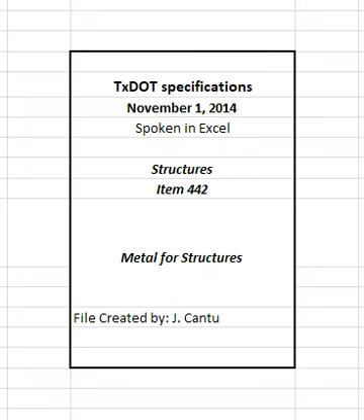Over 2 inches to 4 inches, mechanically fastened: 15 feet-pounds at 70 degrees Fahrenheit. Over 2 inches to 4 inches, welded: 20 feet-pounds at 70 degrees Fahrenheit. Any steel with minimum specified yield point over 65 ksi and under 90 ksi,2 up to 2.5 inches: 20 feet-pounds at 50 degrees Fahrenheit. Over 2.5 inches to 4 inches, mechanically fastened: 20 feet-pounds at 50 degrees Fahrenheit. Over 2.5 inches to 4 inches, welded: 25 feet-pounds at 50 degrees Fahrenheit.